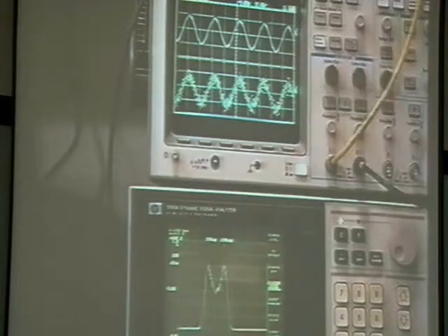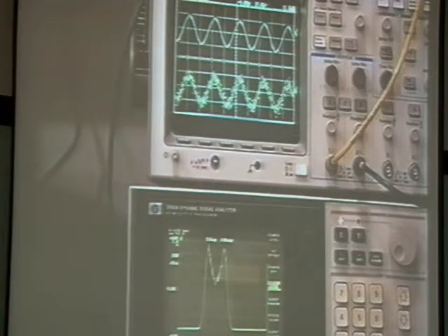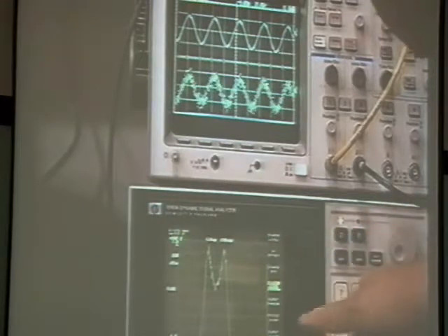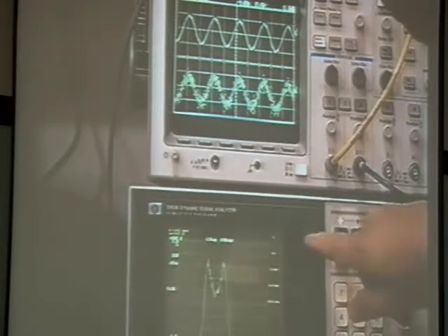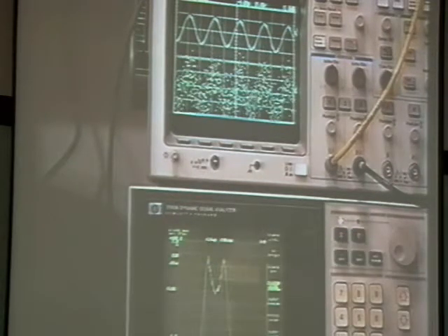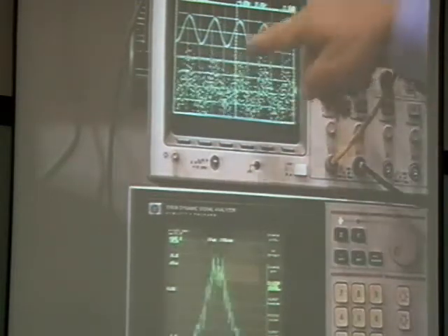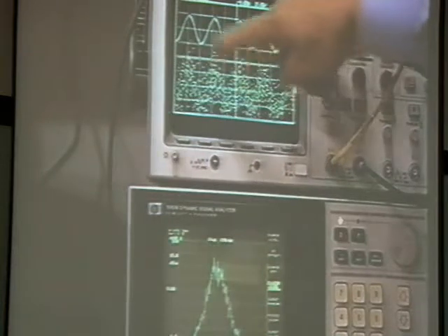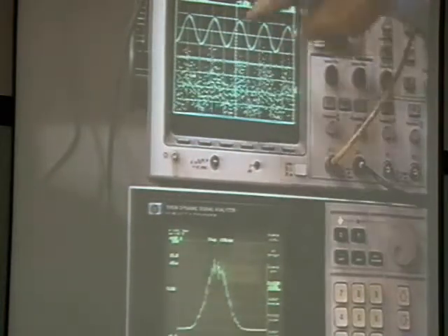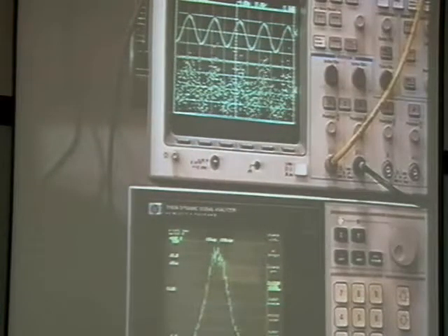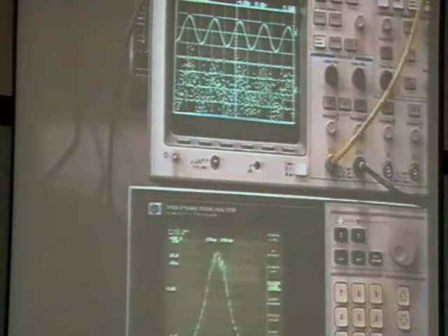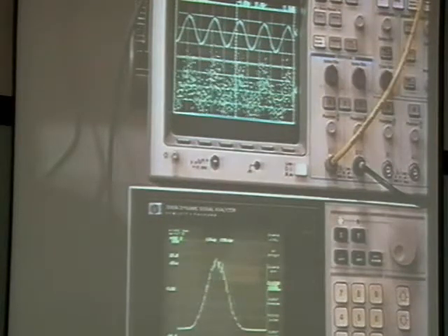Of course, if I increase the random noise, let's say to 4 volts peak to peak, so source level, I'm going to change it to 4 volts, then restart. As you see here, when it's superimposed, you don't really see a well-defined sine because the noise contamination in the sine wave is quite high.